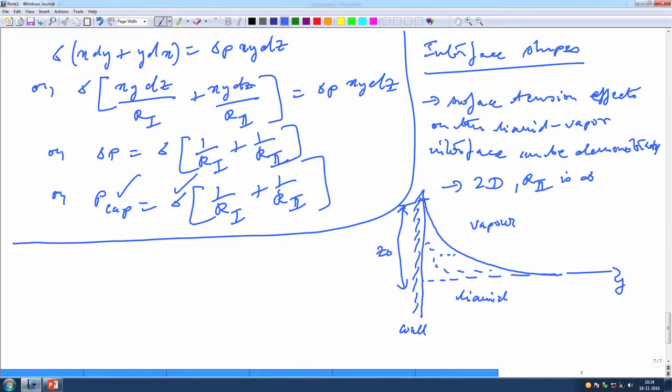So, it is an infinite wall, and an infinite water source, or whatever liquid you can think of. This liquid wets this particular wall, it is a wetting liquid type, and it shows a curvature and goes up the wall for a distance of approximately z0, and there is gravity acting in the downward sense. So, it is a vertical wall and the liquid is wetting the wall, and one radius of curvature is basically infinite. Got it? Okay.